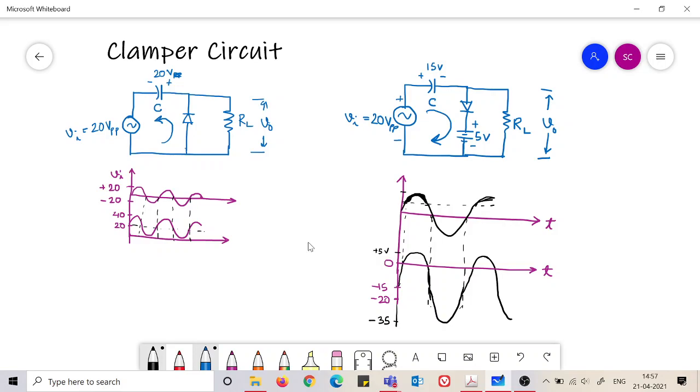When it is reverse biased, some other type of output. When there is a capacitor, then the capacitor will get charged, and after it gets charged, the diode may not come to conducting stage anymore, and the rest of the analysis has to follow with the charged capacitor, with the voltage across the capacitor being considered in the circuit.